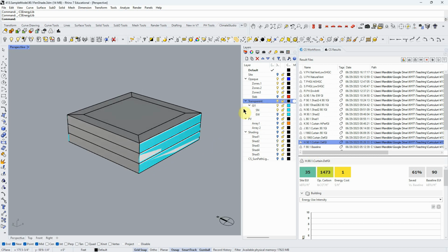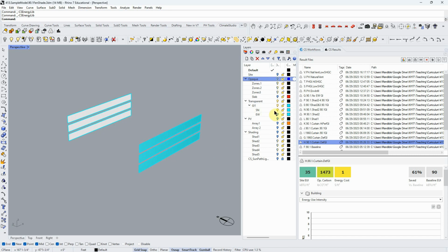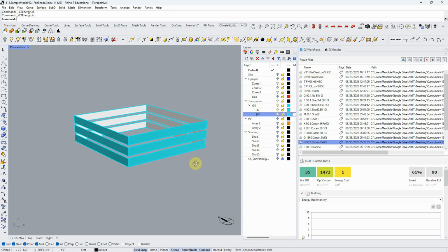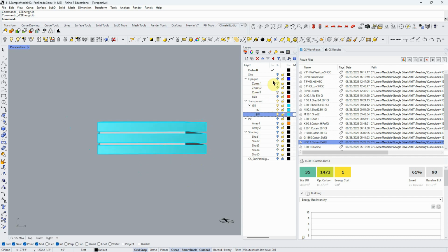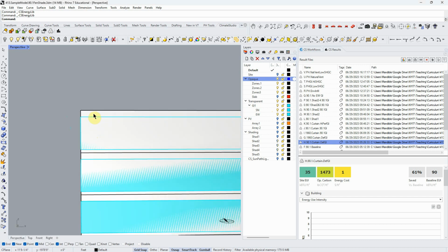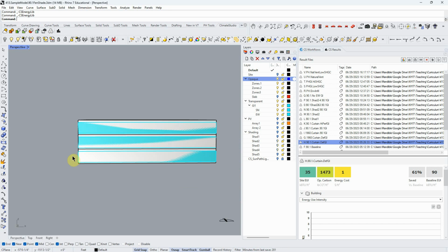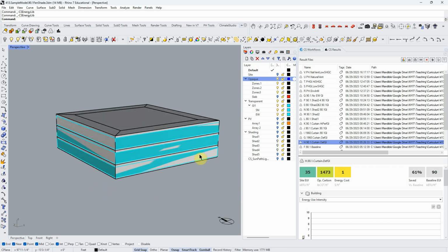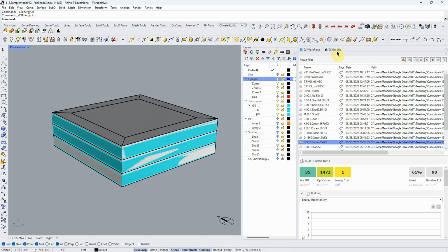The windows I added was a curtain wall. Let me just turn these off. So I did a curtain wall around the entire building. I think it's like 75% so it's somewhat realistic. There's a floor plate and room for mechanicals there, and then there's a slab area down here. So it's a curtain wall with required spandrel opaque envelope. So we got a pretty considerable drop in our efficiency by adding the glass, which makes sense.